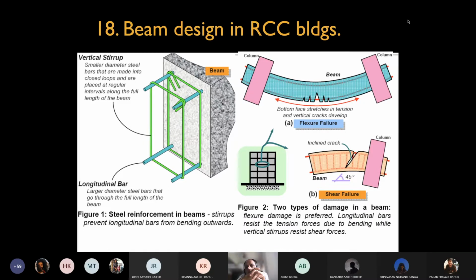Now coming back to the point about earthquakes, it is very important in an earthquake to accept flexural failure as compared to shear failure. Earthquakes are sometimes so powerful that you are not always going to make blast-resistant buildings. There is some economy involved; you will not always be able to afford that kind of reinforcement and stiffness. So the next best strategy is to become resilient.